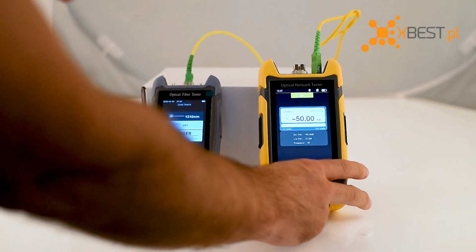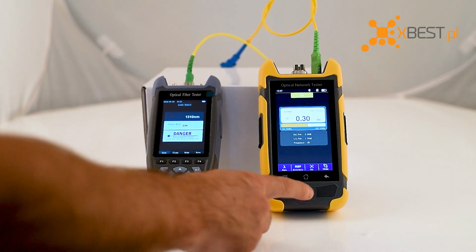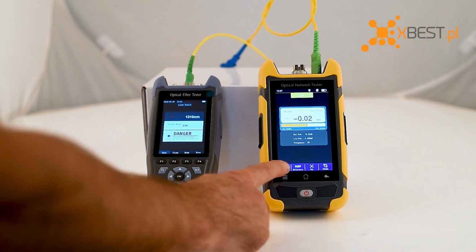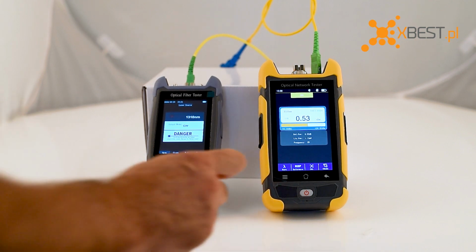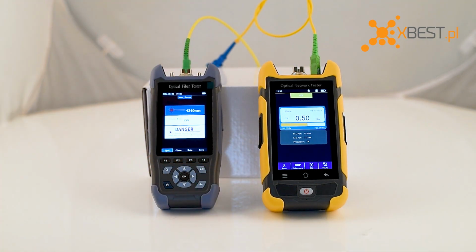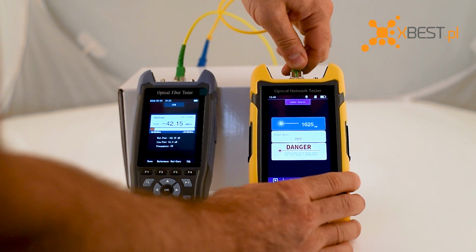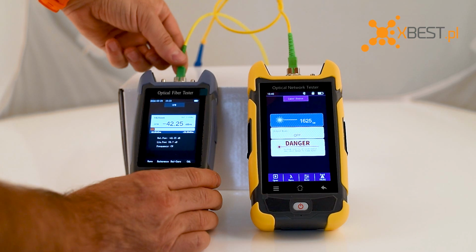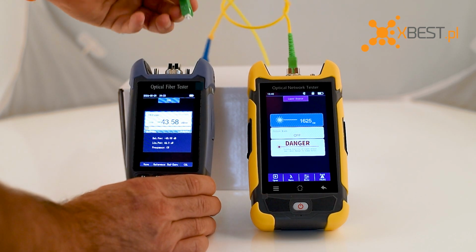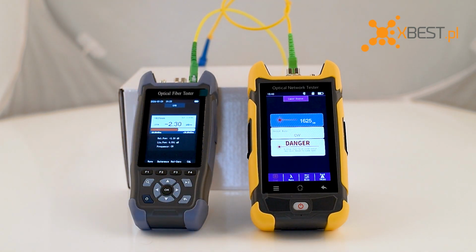Optical power meter measures the power or loss of an optical signal transmitted through a fiber cable. By pressing Wave icon, you can select the appropriate wave in the range of 850 to 1,650 nanometers. Laser source shares OTDR optical port and works on the same working wavelength of OTDR. Press open to activate the laser. By pressing wave icon, you can select the appropriate wave range.